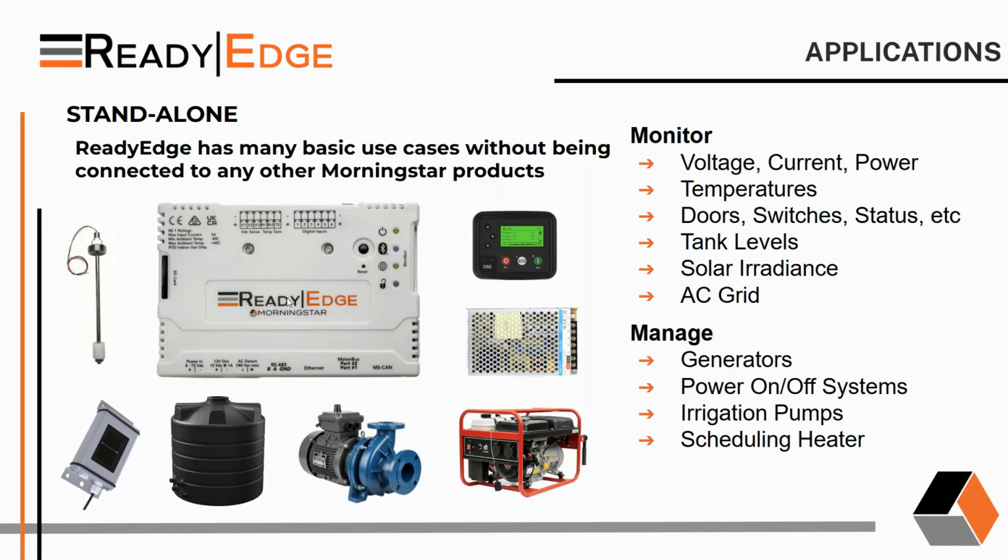I also want to point out heaters in general, whether that's a heater for your box or maybe a heater for an oil and gas cabinet with some sensitive data acquisition unit, or maybe a heater for a lithium battery. It's cheaper to implement a heater that sits outside a lithium battery than to buy one that sits inside the lithium battery. And it also allows you a lot more control as to when you run that heater to make sure that the battery stays on when you need it. And we'll talk a little bit about that with relation to lithium batteries later. One of the challenges, despite all of lithium batteries' great new features that we're getting used to.